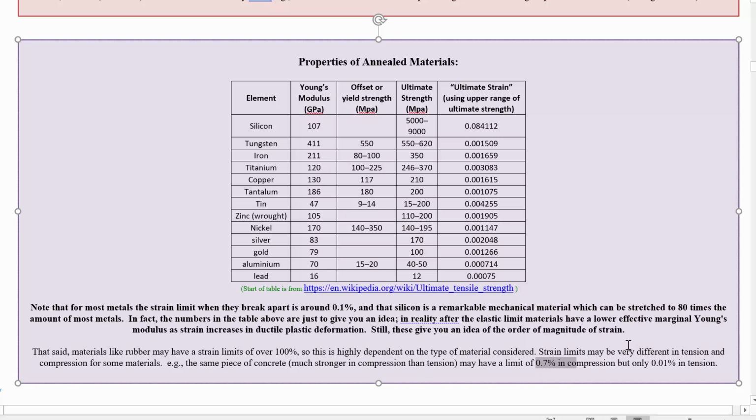Then you pour the concrete in, and you wait for it to harden, and then you release the tension on the steel so that it is going to be compressing and putting some stress on this concrete. If it ends up having the right combination of area and amount that you stressed it by, maybe it puts the concrete to 0.3% compression by default. Then, if it's compressed by 0.3%, it could expand out by 0.31% before it gets to this limit, and it could compress by another 0.4%. So that's a way to get more range on how much stress the concrete could take by pre-stressing it.